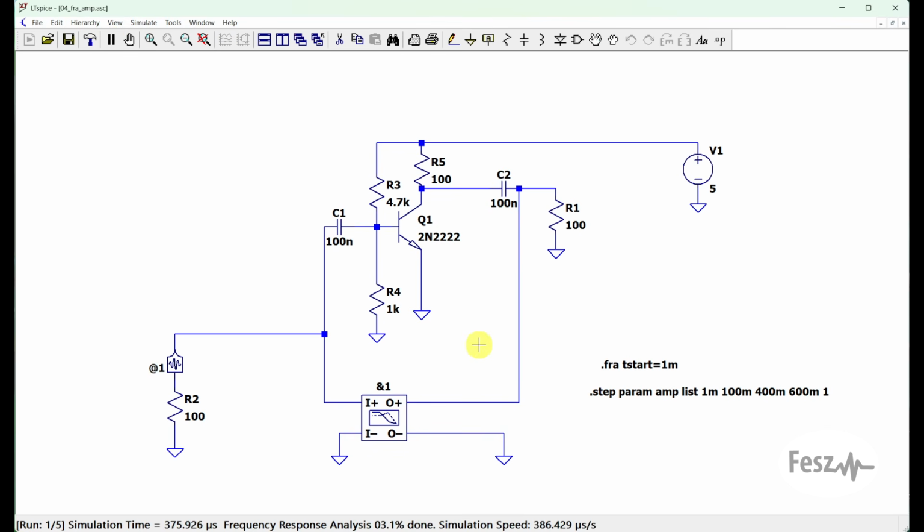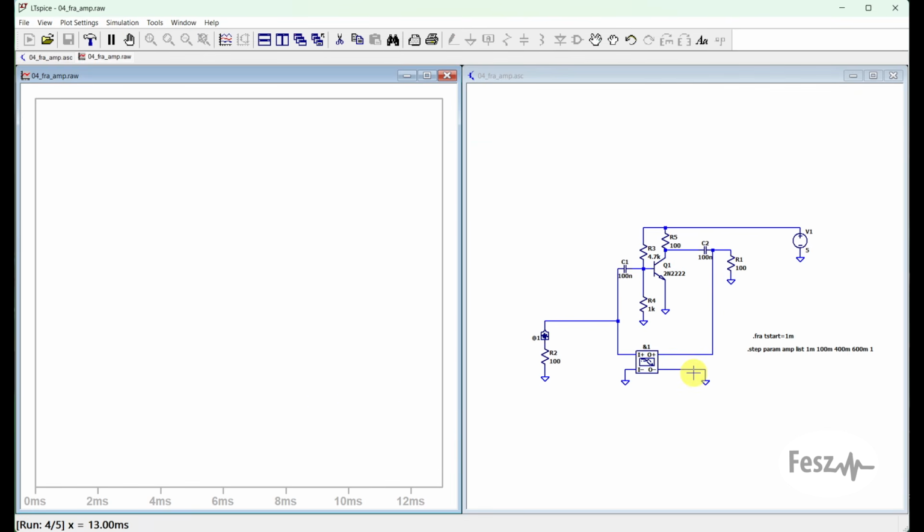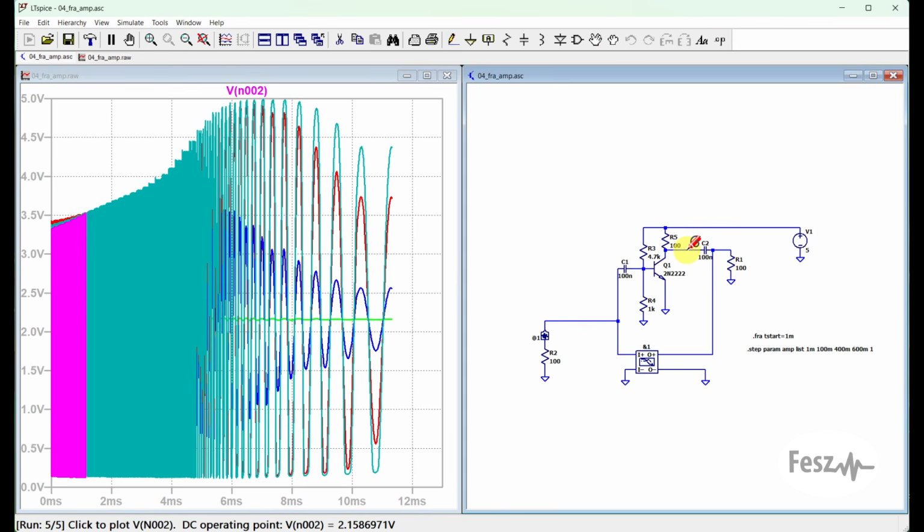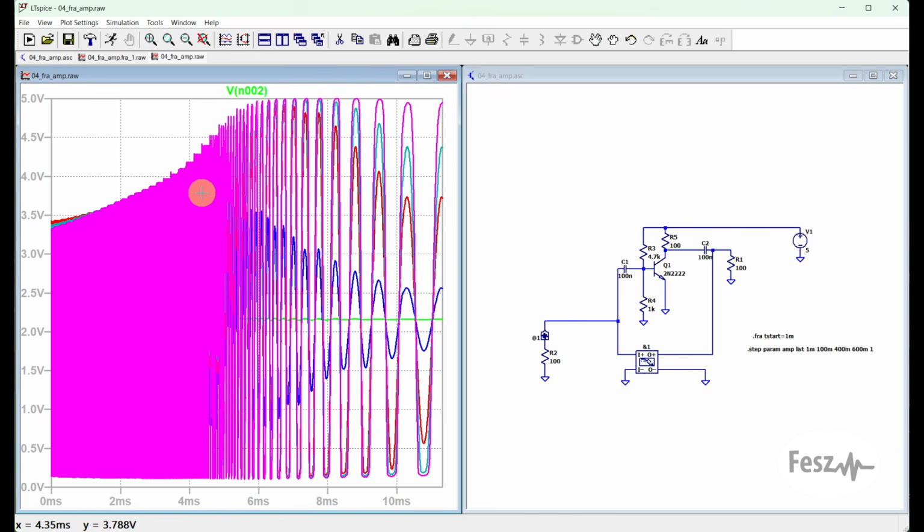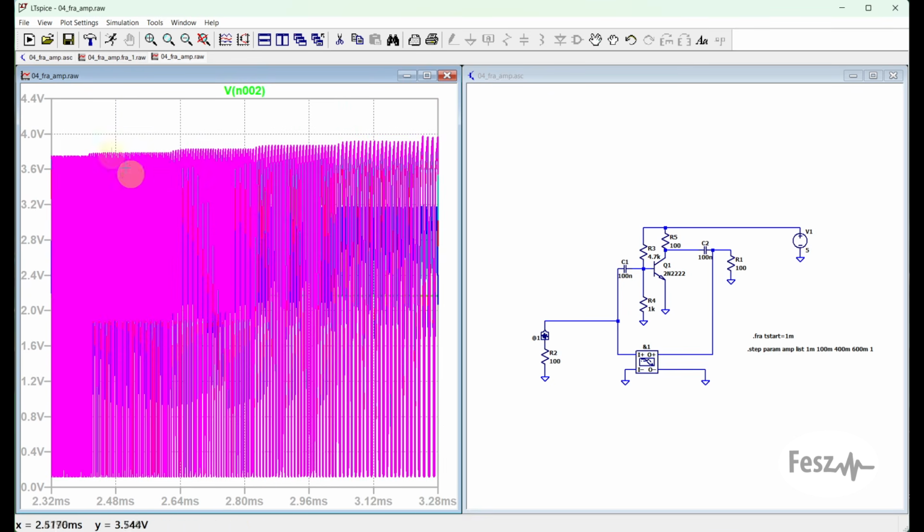So if we run the circuit, we can also probe various nets. So let's say we look in this place. And the first important thing to note is that the circuit is analyzed by injecting a variable frequency signal, but the circuit does not instantly stabilize to the new stimulus. So if we just zoom in a bit, we can see that after every change in step, there is a period of accommodation. So the transition is not instantaneous.